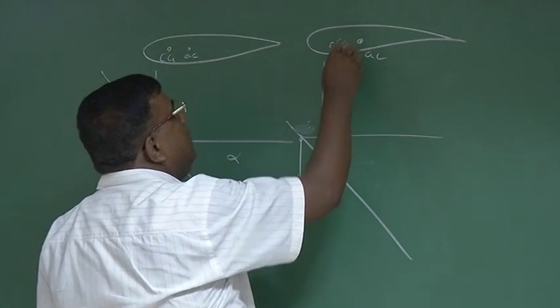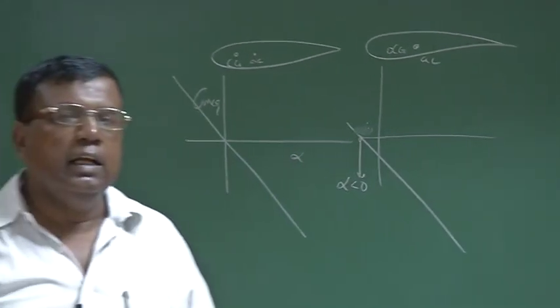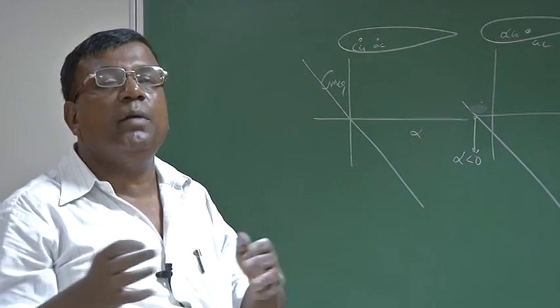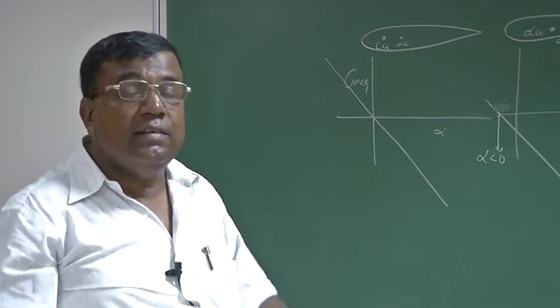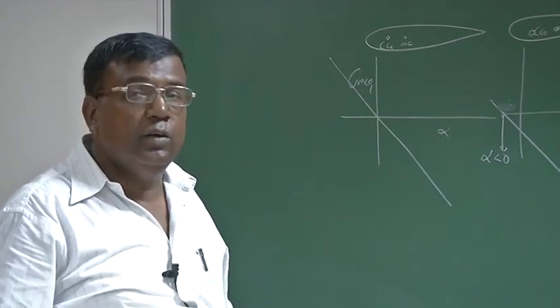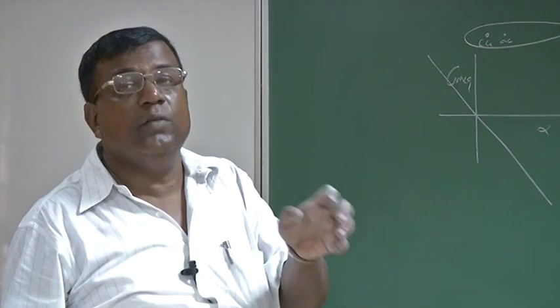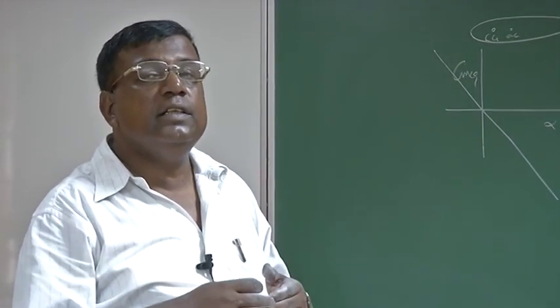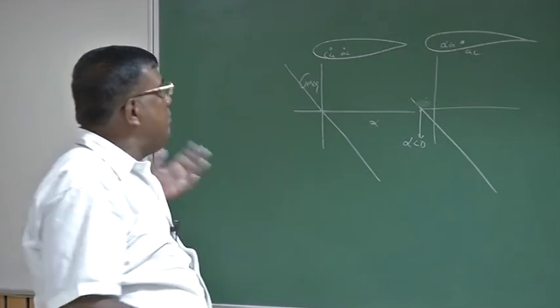This part is clear to us, and both of these configurations are not what we are looking for. That is, if I make a wing alone configuration, whether it has a symmetric aerofoil or a cambered aerofoil, if I just put the AC behind the CG, that is, I do the mass distribution such that CG is ahead of AC. AC is governed by the platform, right? Nothing to do with the weight. But CG I can change by distributing the weight. So I distribute the weight in both cases such a way that CG is always ahead of our aerodynamic center. So they will be statically stable. But my problem is what?